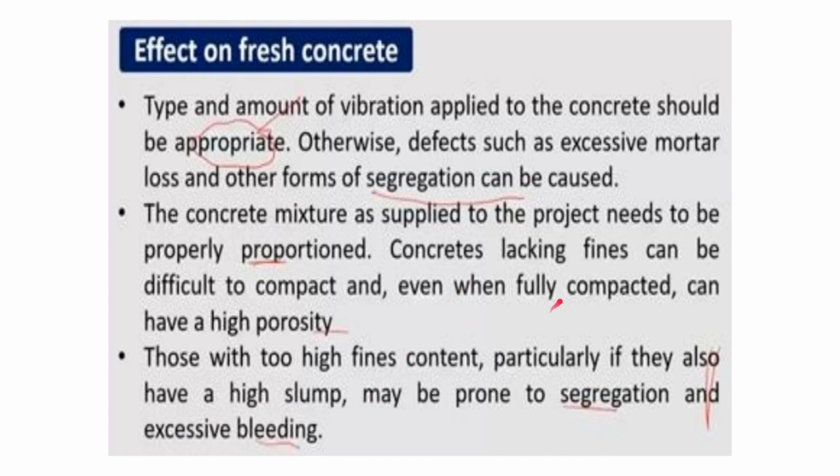So lacking fines is a problem, because it can be difficult to compact and may have high porosity, and having high fines is also a problem, because it may result in segregation, and segregation can also result in excessive bleeding. So there is a trade-off. It should not be too low, and it should also not be too high.